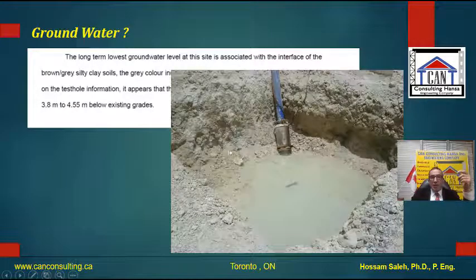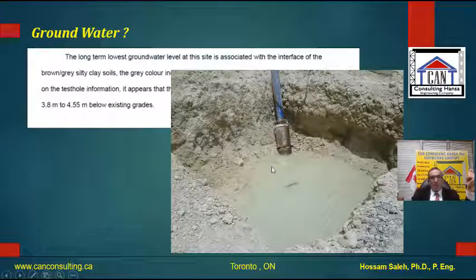How to consider that? You have to look at the dewatering. Dewatering is to get a pump, and then you can have a hose and get this water out of your site. That's very important for the contractor, because that's additional cost, and also for his planning and his schedule. So that's a very important item.